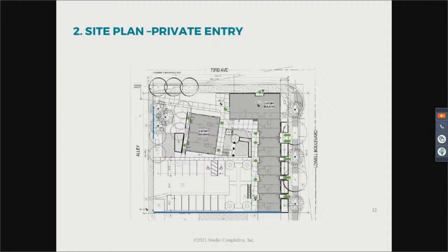Essentially from 73rd South, there are two southbound lanes on Lowell. And thank you, Nathan, for illustrating that. This project will construct a bulb out at the intersection, which will mirror the existing bulb out at the northwest corner. By doing that, it brings the curb line out, and we will eliminate the second southbound lane and allow parking there along this frontage. And then south of this property, it'll start to transition into that right lane must turn right at 72nd Avenue.